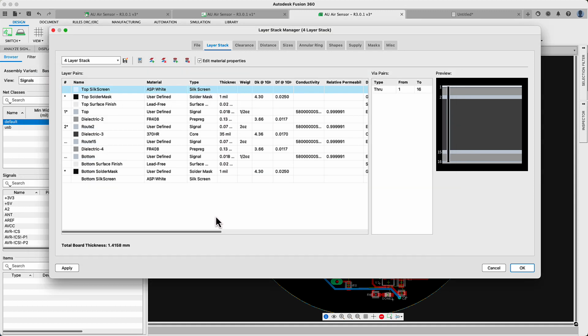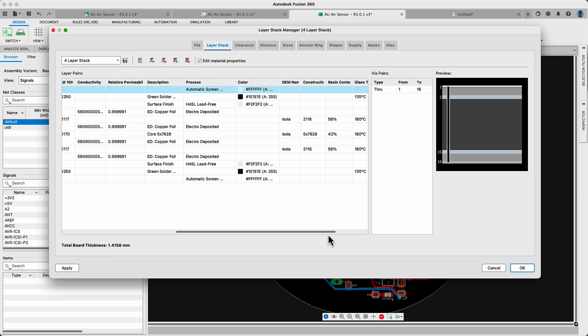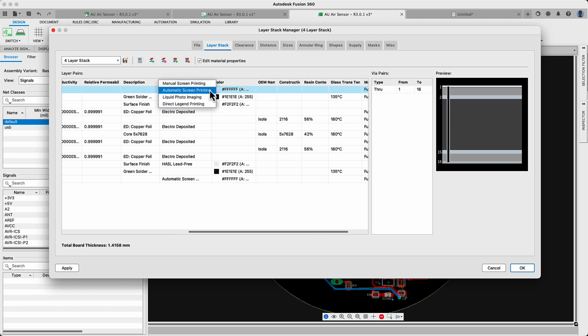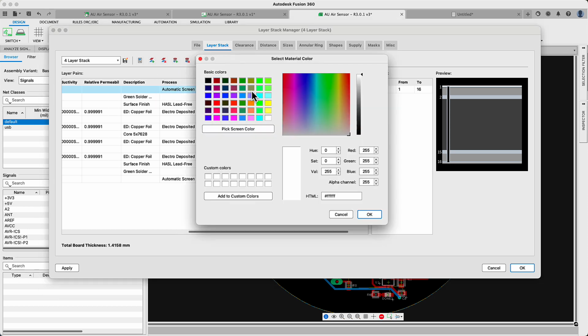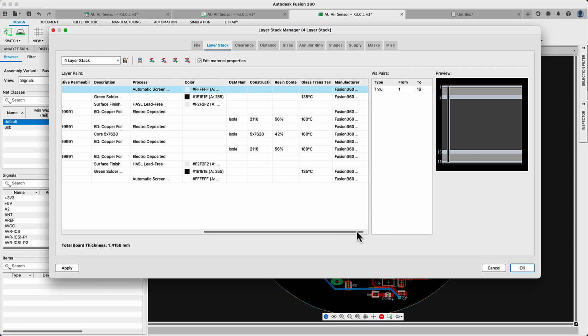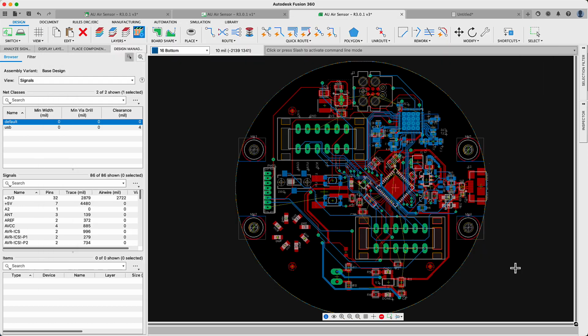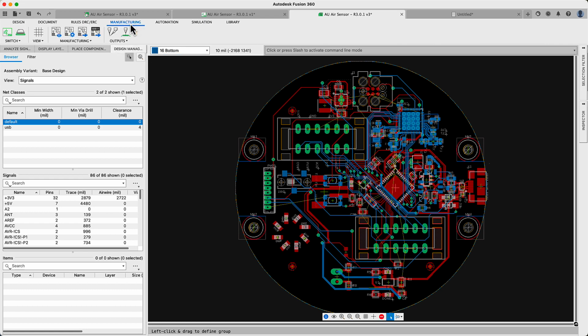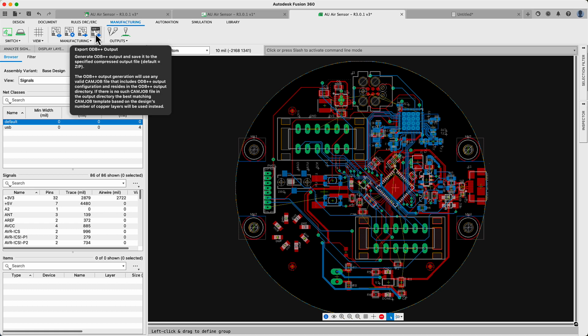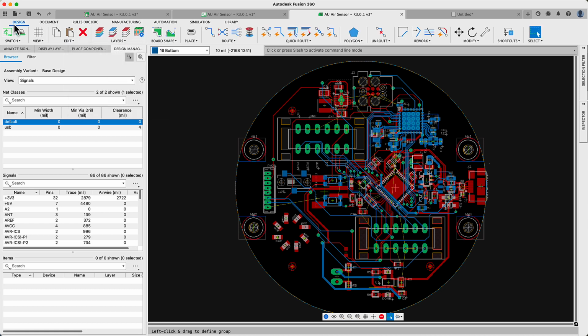Silkscreen is a layer of ink trace used to identify components, test points, parts of the PCB, warning symbols, logos, marks, and more. Since the silkscreen ink is not conductive, it can damage the quality of electrical contacts when it mistakenly protrudes into solder mask clearances, resulting in the scrapping of assembled boards if the flaw is not identified during the electrical testing. Creating high fidelity layer stacks makes it easier to detect possible defects far earlier in the design process.